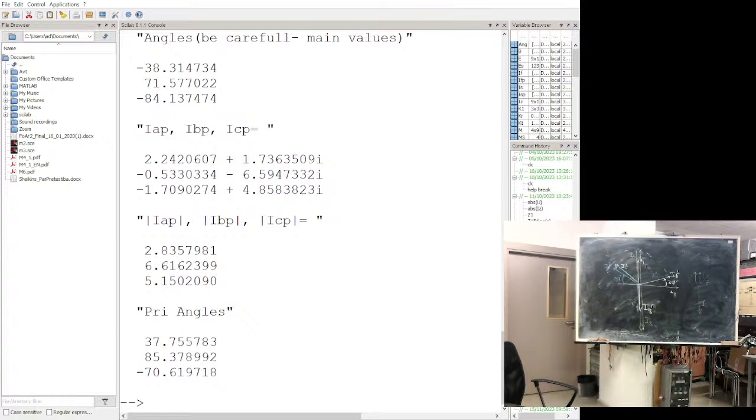For the B phase, I'm measuring phase B. You see, current increases. Voltage decreases because it's a fault. You see the lamp, but current increases. And on C phase, I'm measuring phase C of the motor.